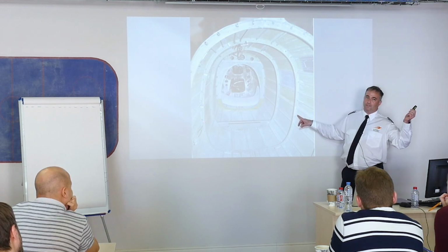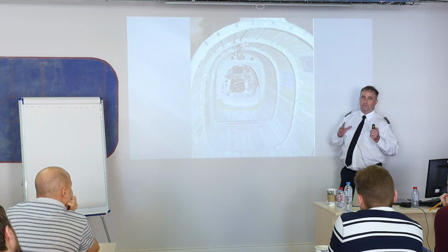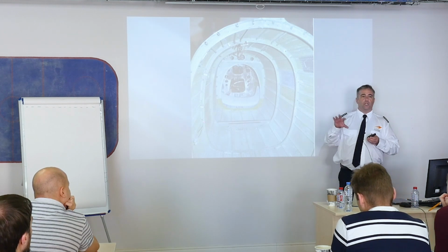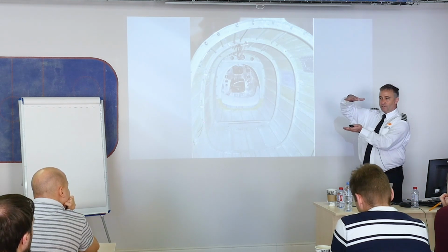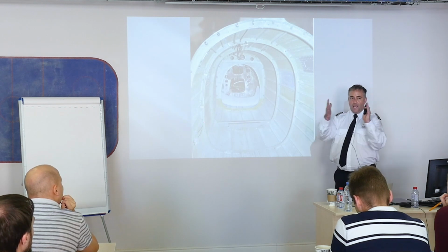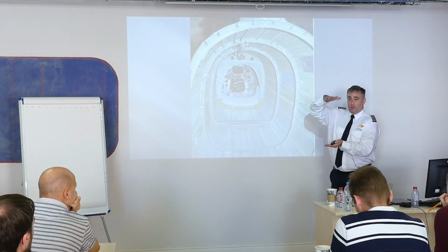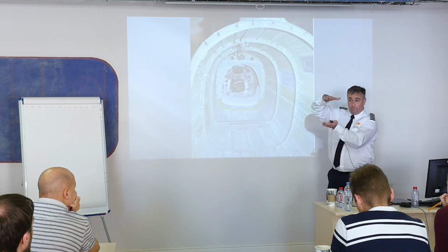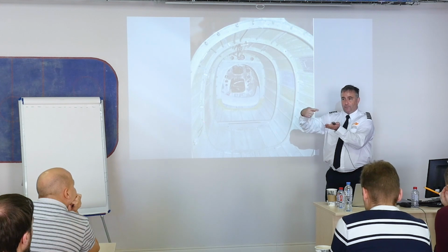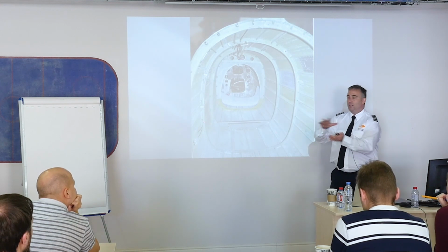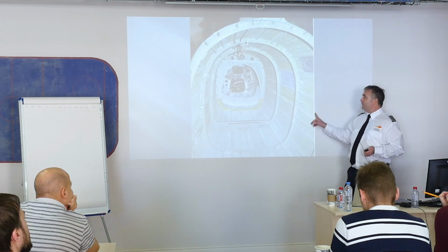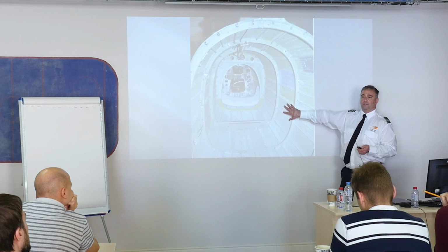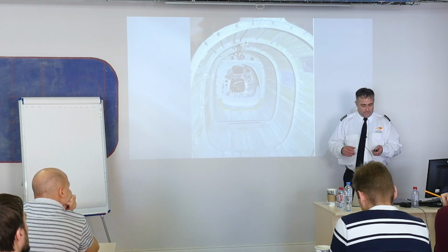if you think about how the sheet metal design works, remember the Cirrus is all composite. It's built out of carbon fiber and some sort of plastics, right? If you think about how sheet metal works, consider a Coke can, right? You got a 12-ounce Coke can or a beer can or whatever. I could put a lot of weight on it. I could probably even stand on that Coke can, and it will maintain its shape. But if I poke it just a little bit on the side, then it'll crumple, right? The same thing would happen with this if I didn't have the longerons and the stringers. So this is the semi-monocoque design. Without that is a monocoque design.